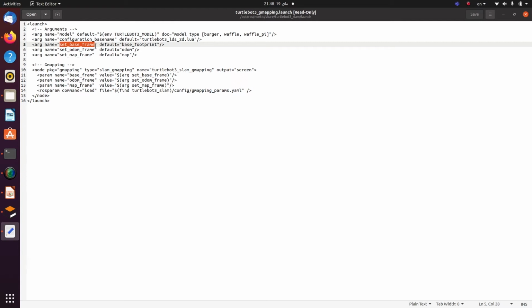So you have to define the frame of each sensor, right? And you've got to relate them to the base frame, because eventually you need to reference everything to the base frame of the robot, not the individual sensors, but the base frame itself, so that we can have all the readings consistent and referenced to the same local frame, right? And then we're going to compare this local frame again with the global map frame. So there are a lot of frames, and we need to define the relationships between all of them.